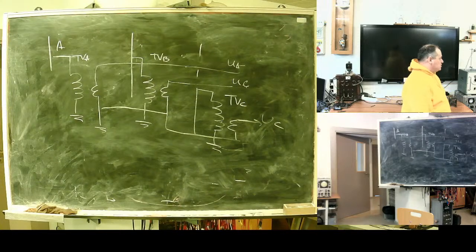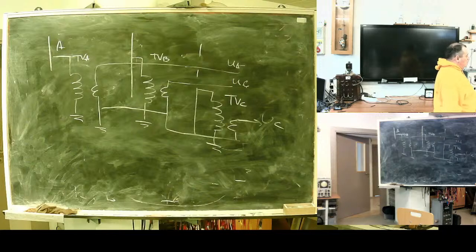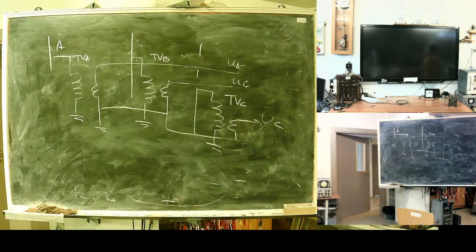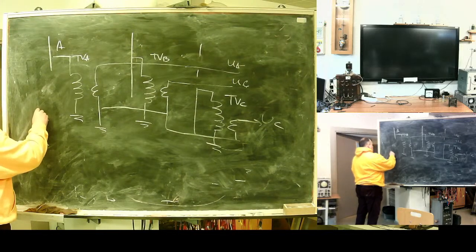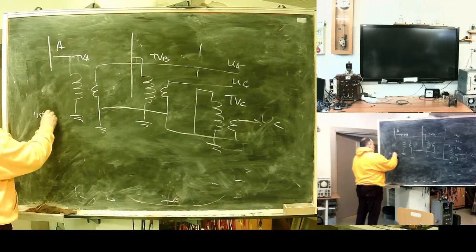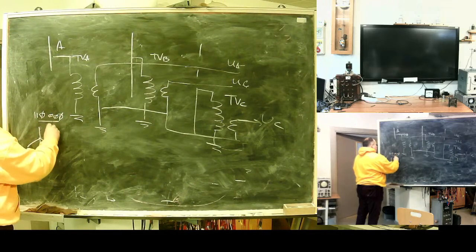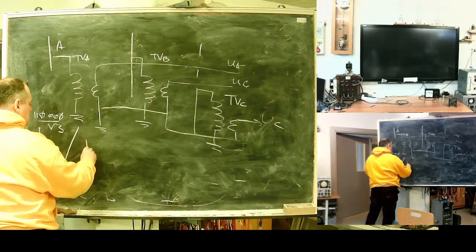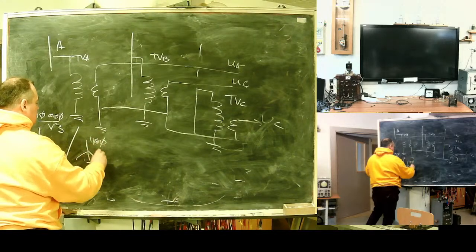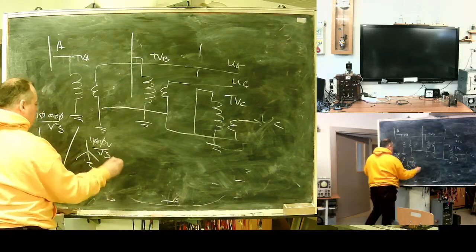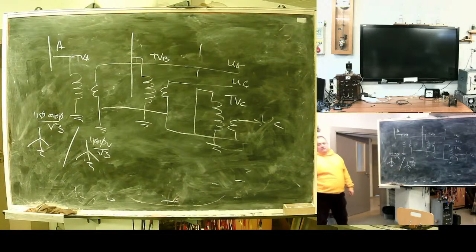3-phase blocks are also produced. This thing is nice, but this is for phase voltages. Connection schematics, for example, grounded star: 110,000 divided by square root of 3. Secondary voltage, also star, will be 100 volts divided by square root of 3. In case of phase voltage, 57 volts. This is fine.